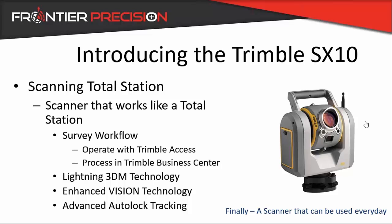Does it export processed point clouds based on traditional survey control? Yes, that was one of the key features as well. It's using a traditional workflow because you're operating the instrument with Trimble Access. So all the point cloud data, including your total station data, your control data, everything is on that same coordinate system. Traditional survey workflow.